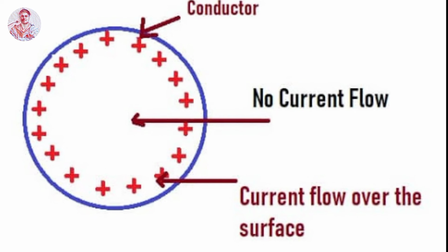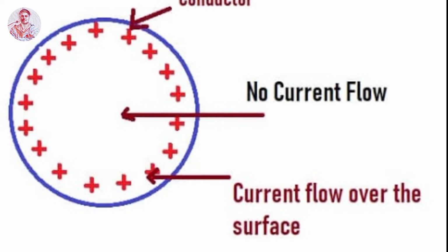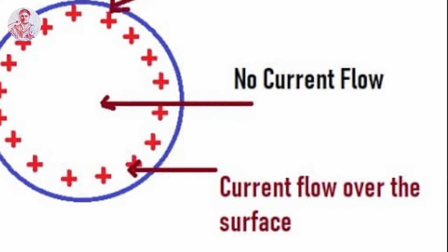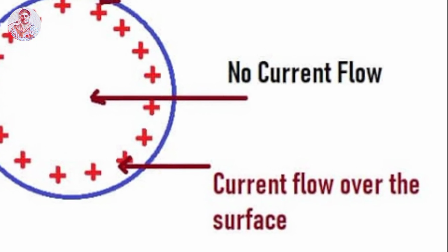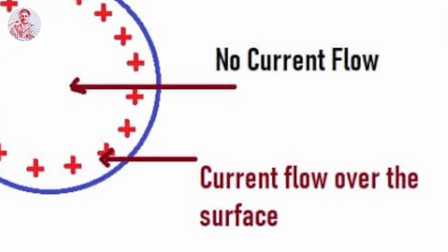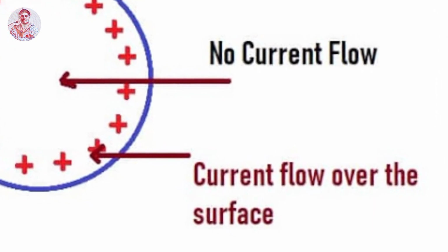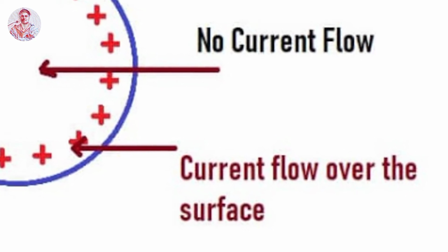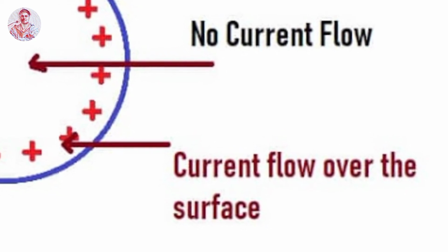The fourth limitation is skin effect. This effect appears at higher frequencies, when the current flows from the smaller cross-sectional area to the outer surface of the conductor. As the frequency increases, the resistance of the conductor increases. Due to this, higher frequency losses are produced.